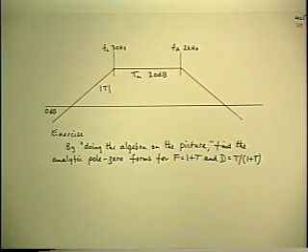Gain drops off above that. So we've now arrived at the fundamental property of the feedback system, and the next step is to determine the derived quantities, namely F, the feedback factor, which is 1 plus T, and then the discrepancy factor, which is T over F.